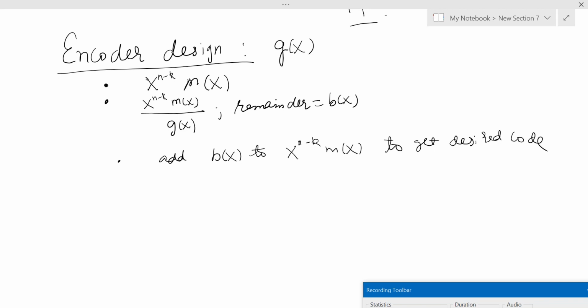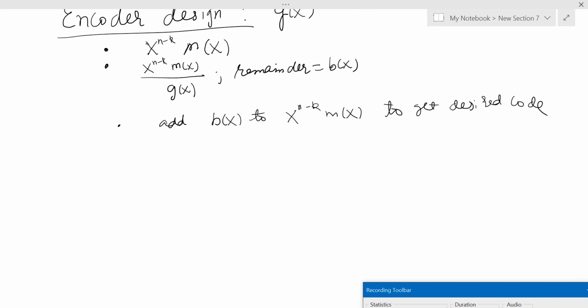And so what will be the rules? We have here a flip-flop. It simply stores a bit, and whenever the clock ticks in, whatever is at the input is stored, and whatever is inside the flip-flop comes out of the flip-flop. That is the simple rule of a flip-flop. Okay.